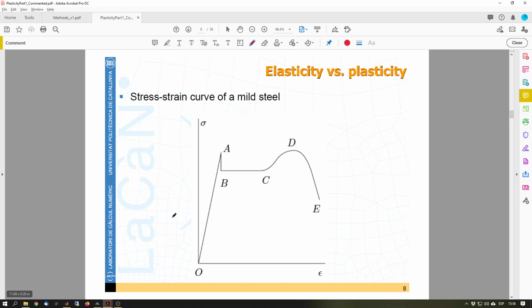So we have a stress-strain curve, and what is happening in steel, for instance, which was mostly studied in the 40s and 50s. We have an initial branch, then a softening, a sudden drop and a plateau, where we can keep increasing the strength. We have a test like that: I keep pulling, imposing a certain strain, and I measure the force that I need to impose this strain.